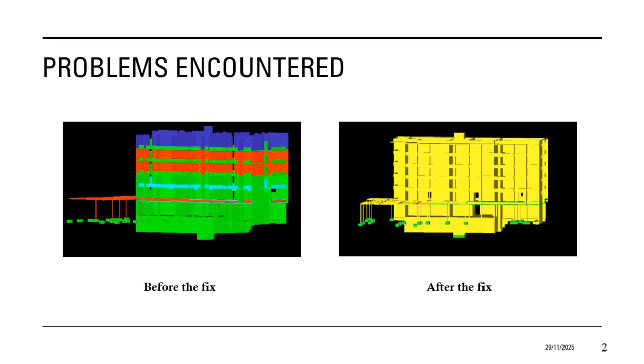A problem that surged was the fact that the formwork removal, indicated in yellow, doesn't appear in all of the building at the end, even if we configure the order of the process properly. The visual error is due to an incorrect configuration in the Timeliner, specifically in the end appearance parameter of the task. The fundamental problem is color overlap in the 3D model.